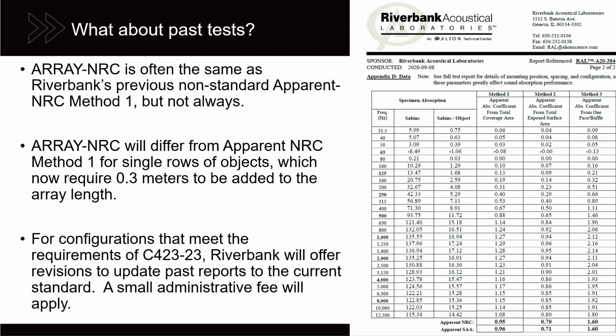So. All right. Will there be a standard size and configuration of baffles when testing? Example, baffles must be 12 by 48 inches. Spacing must be X between units. Yep, good question. So it currently exists a standard mounting for baffles. ASTM E795 is the mounting standard.